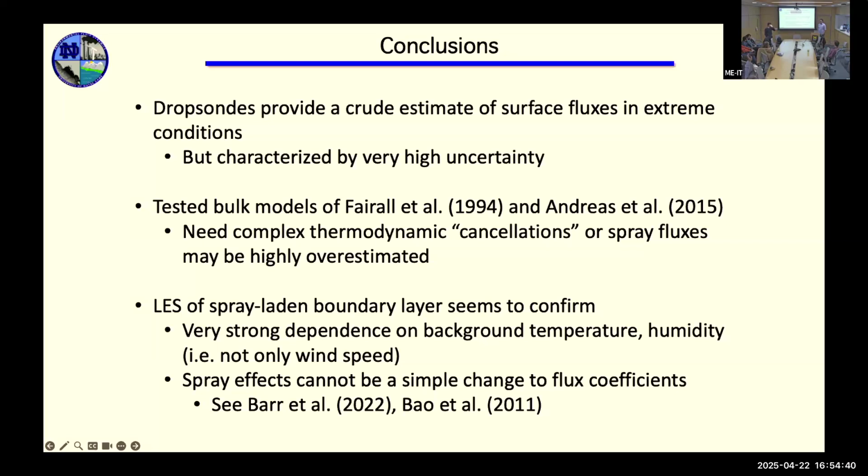Questions? Yeah. In your LES, I was curious, the droplets here are Lagrangian, but of some size. What kind of scales do you think you're resolving in the turbulence? Yeah, I mean, there's a huge discrepancy, right? The grid spacing is like 5 meters. And so you've got a 20 micron droplet in a 5 meter grid box. I'm not even bothering to put in a subgrid correction because it's just going to be random noise at that point.